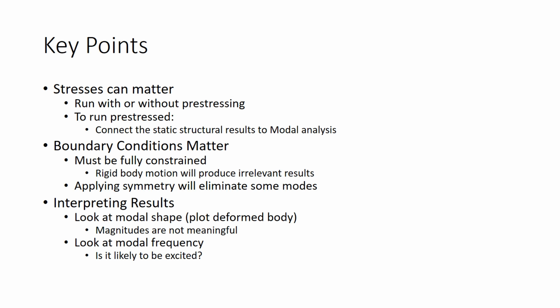First of all, some key points on modal analysis. One is stresses can make a difference, so you can run with or without pre-stressing. In essence, pre-stressing many times will stiffen the matrix so that it responds differently than the unpre-stressed state, usually with higher frequencies.